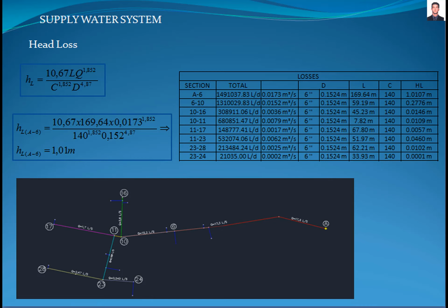The diameter is selected by iterating process according to the losses, with a good judgment trying to select a diameter that generates adequate losses for a good performance cost criteria, taking consideration the minimum diameter allowed by the American Water Works Association M31 standard, which is 6 inches.